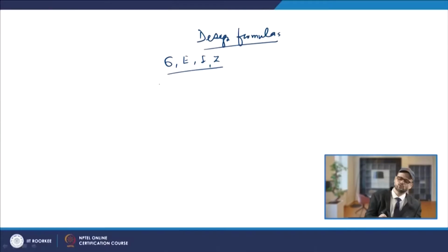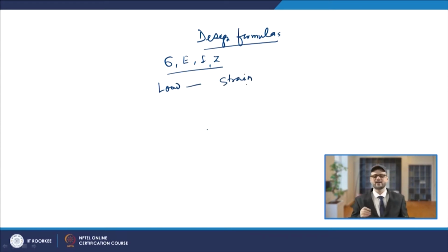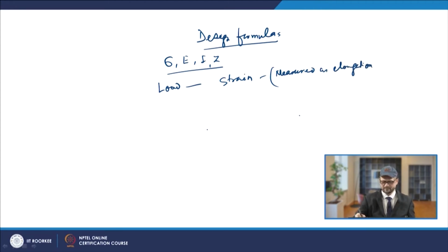So load will be creating strain, and this strain is measured in many terms. You may have the strain as elongation, or contraction, deflection, or angular twist.